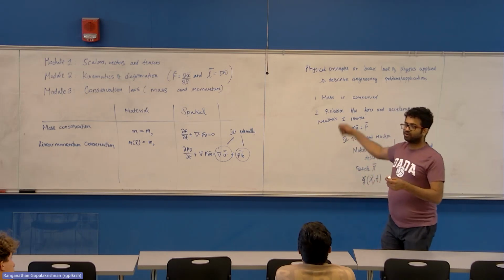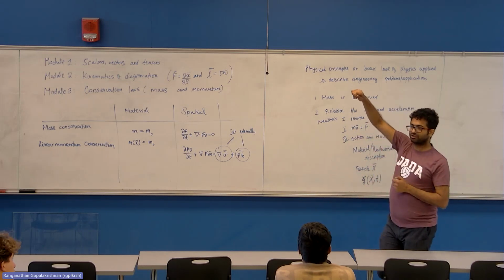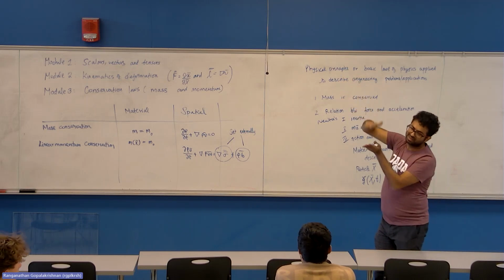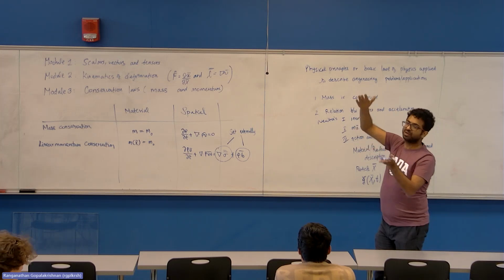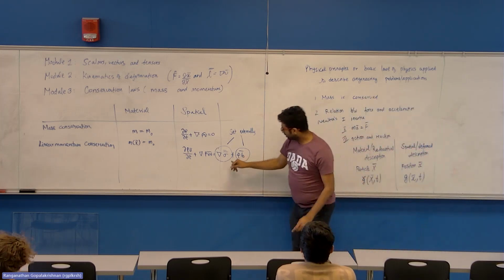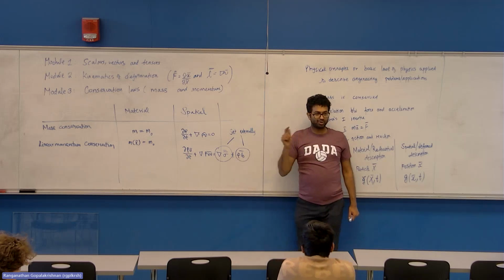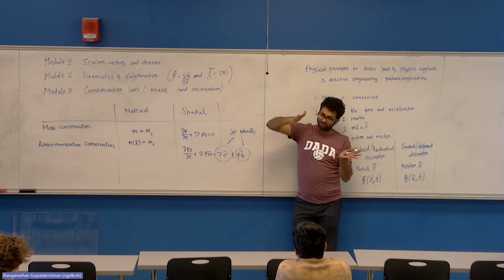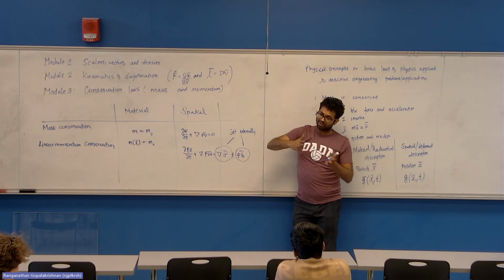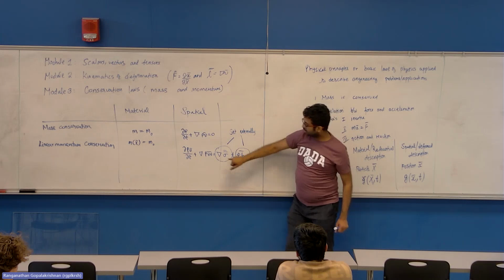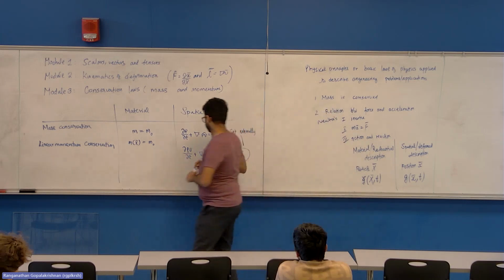Deformation, and you are also monitoring the force transducer in your loading machine to see how much force you are squeezing with versus how much the length is changing until something breaks, right? So that loading, you should understand, is set by you. You get to operate the testing machine. You get to say how much force to apply to squeeze that sample or to pull apart the sample. So this is set by the user, and this is the response of the material.